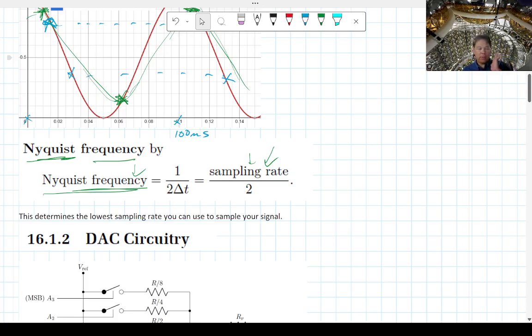So that's a good thing to know for both analog to digital conversion and digital to analog conversion. You need to sample enough of the wave so that you get the shape. This is the minimum, not the usual. Usually I would go with at least 5, make this denominator at least 5, and that way you're sampling multiple points on the same wave.